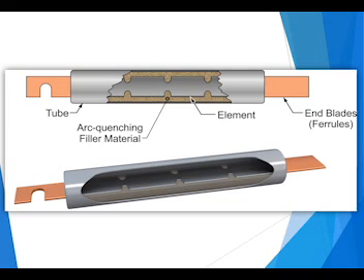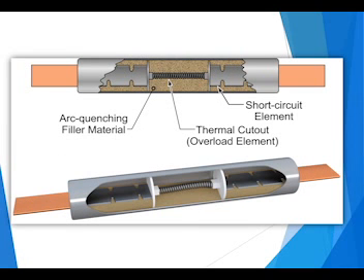and therefore stop the circuit from operating. And there's 2 different types of fuses that we can use. The one you see on the screen right now is called a non-time delay, which is a single element fuse, and it will interrupt current immediately on an overcurrent condition. In some cases, we would want to have a time delay fuse, which is a dual element fuse. Some equipment has a very high momentary inrush of current, such as motors and transformers and capacitor banks. So therefore, the time delay will prevent any nuisance tripping for these items. If the current remains high, then the fuse will still open.